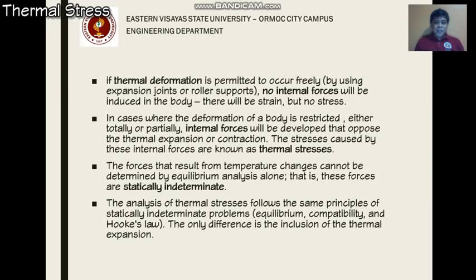The stresses caused by these internal forces are known as the thermal stresses. Since the bar is not allowed to elongate or contract, internal forces will develop in the form of tension in the case of elongation and compression in the case of contraction. Forces that result from temperature changes cannot be determined by equilibrium analysis alone. That is, these forces are statically indeterminate.